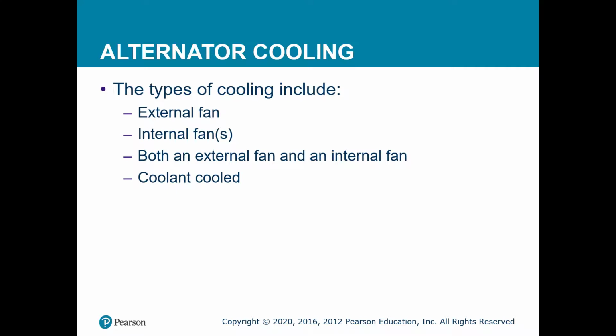With alternator cooling, there are many different ways of trying to keep it cool, because obviously turning a rotor on and off is going to generate heat. The stator itself is going to generate heat from current being induced through it or voltage being induced through it. The diodes are going to generate heat by rectifying the AC voltage to DC voltage.